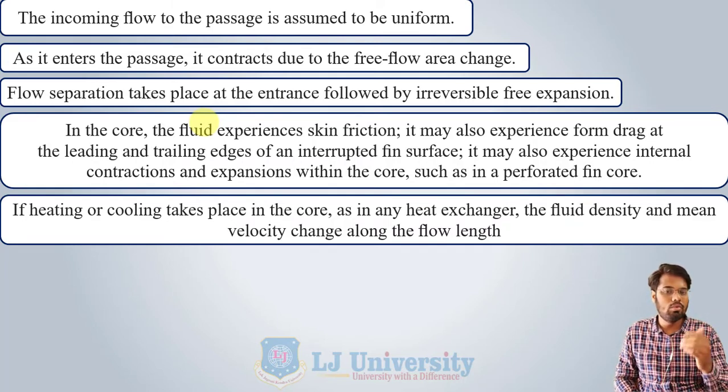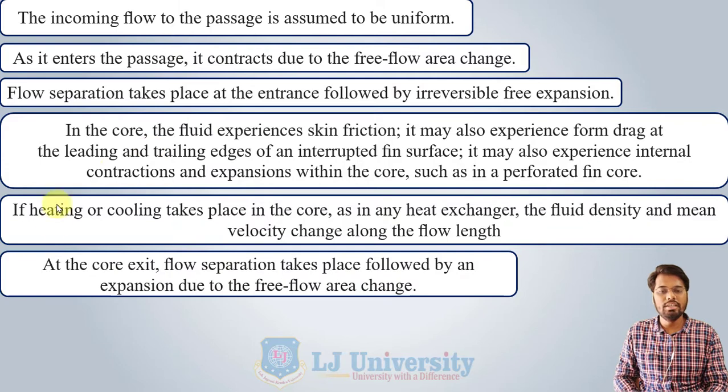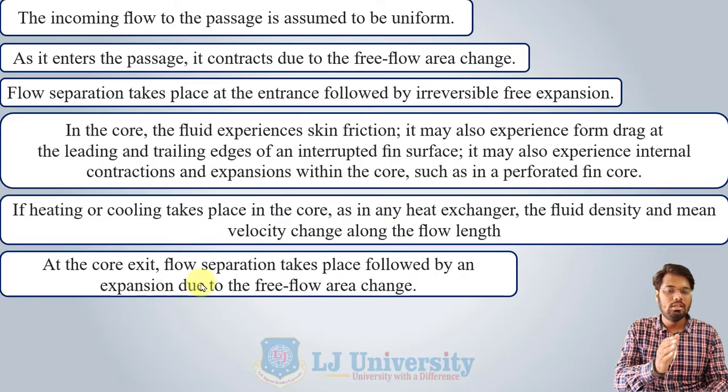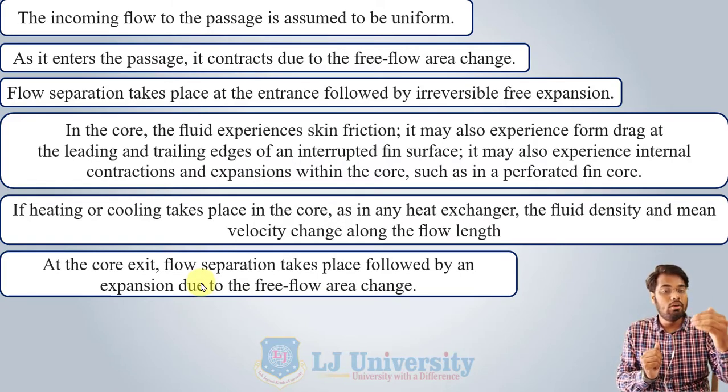Due to that heating and cooling in any heat exchanger, the density of the fluid, either air or water or cooling oil, is going to change along the flow length. So at the core exit, flow separation takes place followed by an expansion due to the free flow area change. At the entry point, the free flow area changes due to the contraction. Within the core, due to heating or cooling, the density of the fluid is going to change.